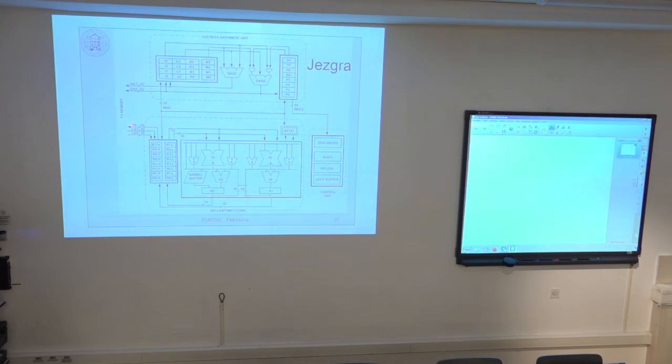It is 32 bits wide and it is only a single one, which means that in a given instruction I can store the value from some of those registers, for example R3, as a 32-bit value into memory based on address either DA0, DA1, doesn't matter, but only one store in a single cycle. I cannot have 2 stores in memory in a single cycle because I have only one bus to do the store. I have 2 buses to do the load.